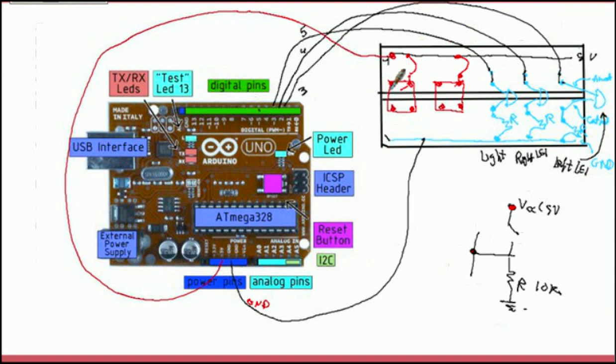The second point should go to pin 9, as we said, we select 9 and 10. The second one goes to 10, digital input. So of course 9 and 10 have to be programmed as inputs. 3, 4, and 5 have to be configured as outputs.